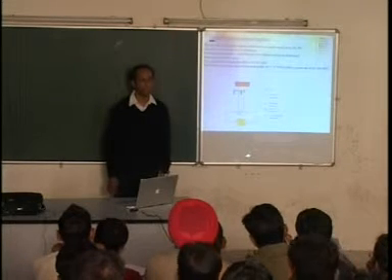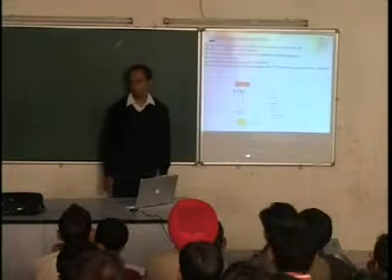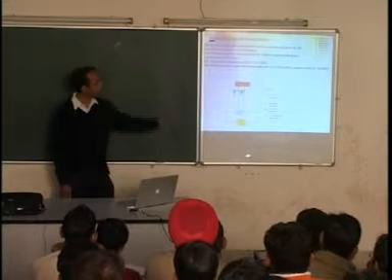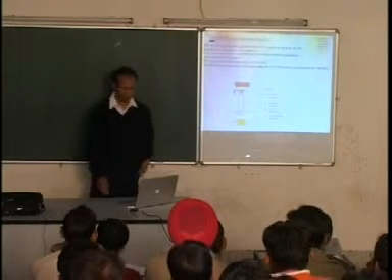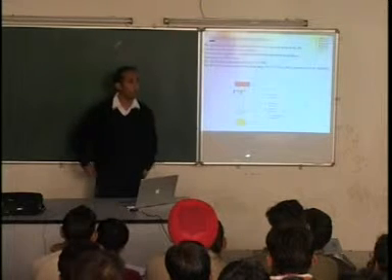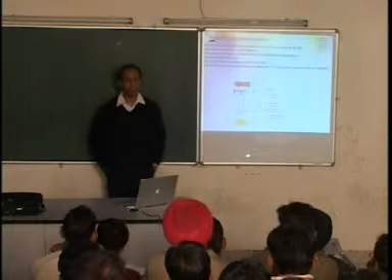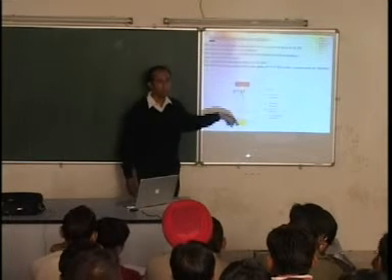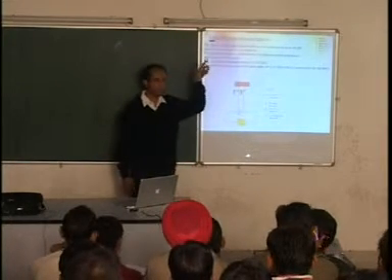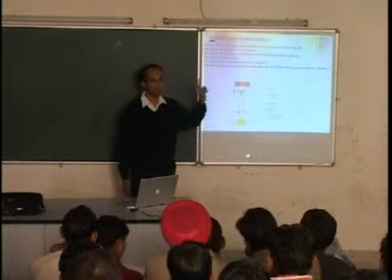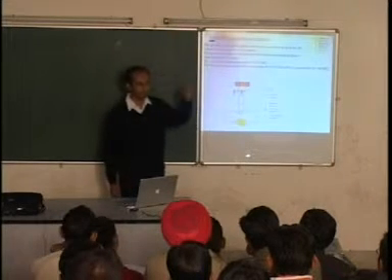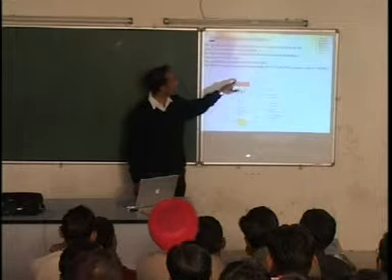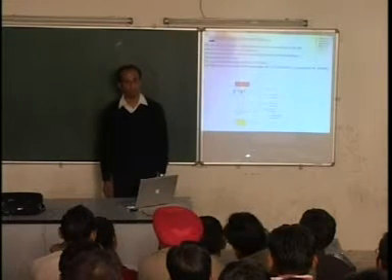That's done. Okay, so this is the idea. These are standard practices. So when I told you that old-fashioned BJT amplifier with some modifications, these are the modifications. Resistors, those 4 resistors, actually we don't use 4 here, we use only 3. That emitter feedback resistor is not used.